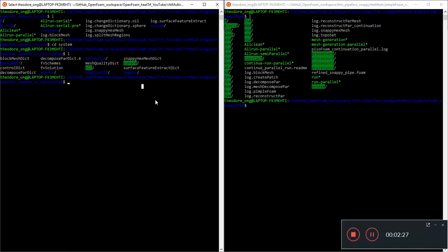Now, to see what files we need in here and here, we'll need to check what is inside the original files. Meaning to say, for our oil and sphere regions, there needs to be fvSchemes and fvSolution and some other kind of files in there as well.